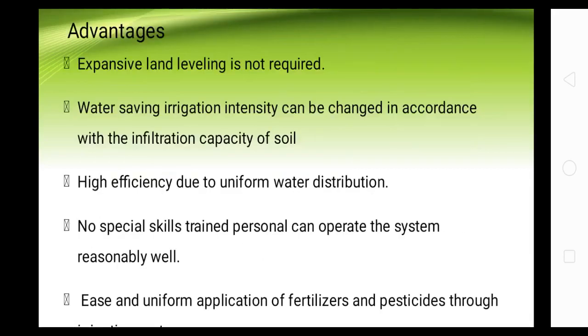These are the advantages. First, expensive land leveling is not required. Water-saving, irrigation intensity can be changed in accordance with the infiltration capacity of the soil. High efficiency due to uniform water distribution. No special skilled personnel are needed; trained personnel can operate the system reasonably well.